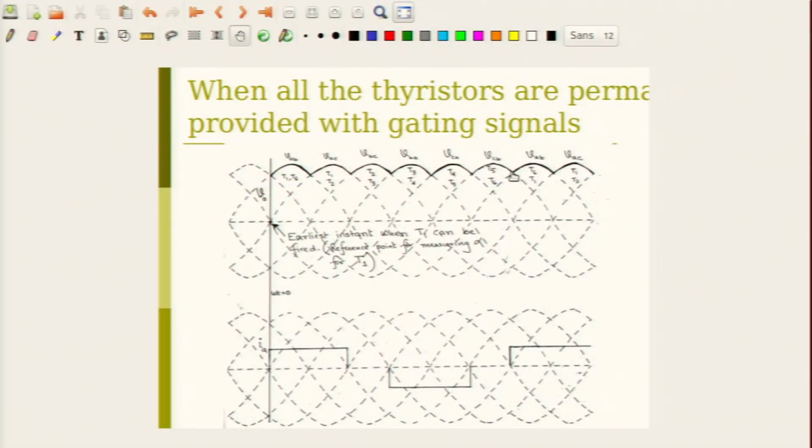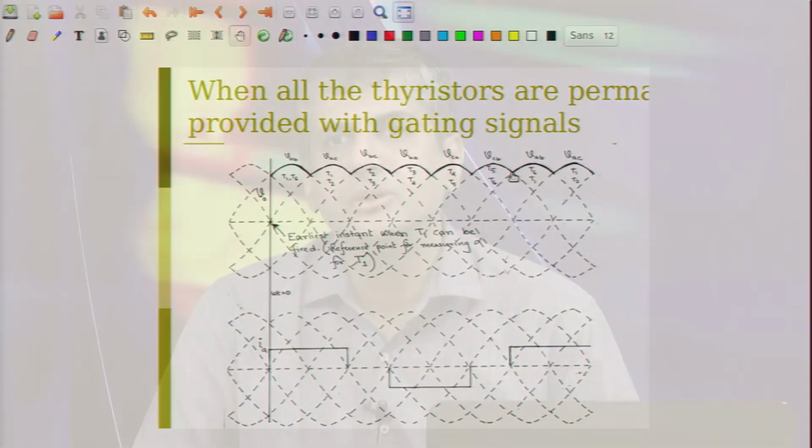So, in fact, we have done this circuit before, it is a 3-phase diode rectifier. So, you have got the lowest harmonic component on the DC side voltage is in fact the 6th harmonic, and 12th harmonic and multiples of 6. The lowest harmonic is of course the 6th harmonic, that is, if you have got a 50 hertz input AC waveform, you will have 300 hertz as a minimum harmonic which appears.